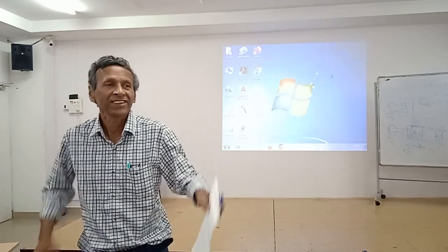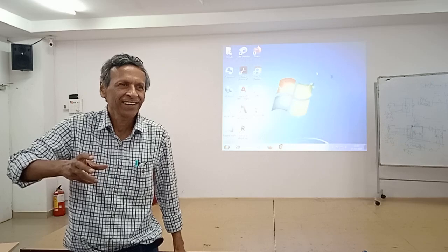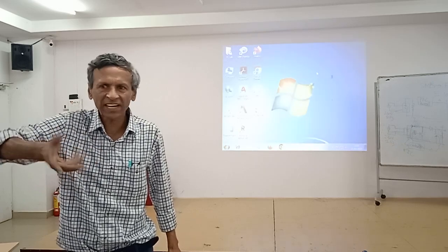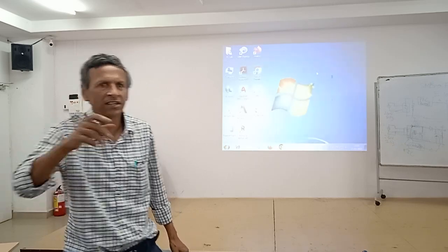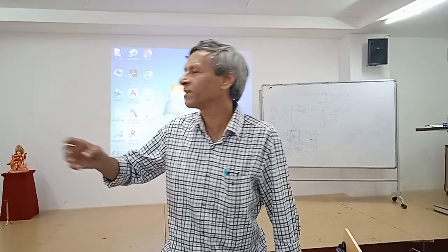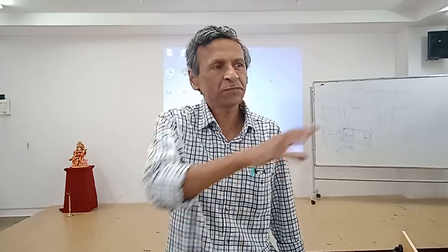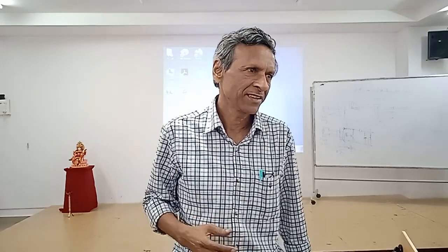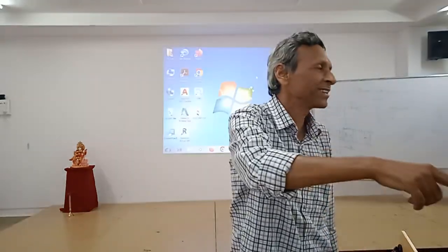Brush is a commutator. Now suppose the motor rotates back and forth or in a single direction, there will be wear and tear on the brushes. So after some years of operation, you have to change the brush. So it is a major repair. Otherwise PMDC was good enough in earlier years. That's why the BLDC word came into existence.